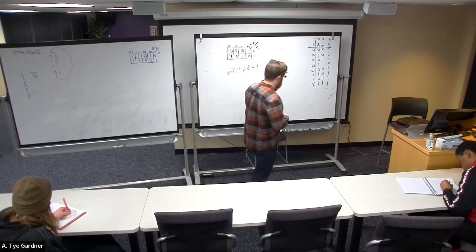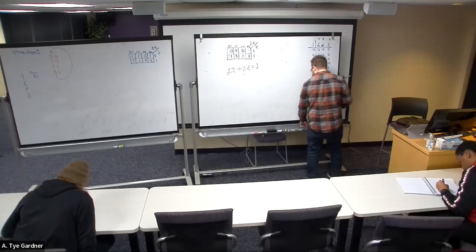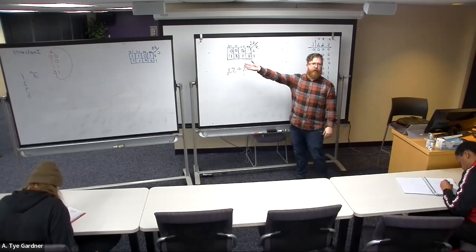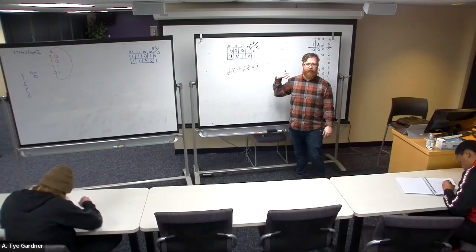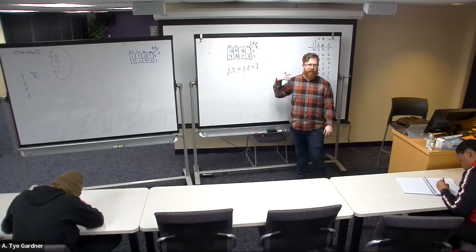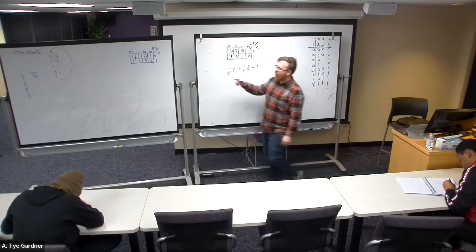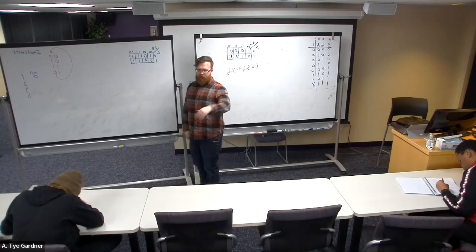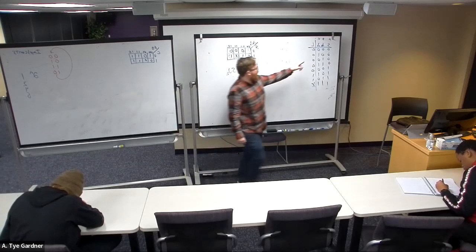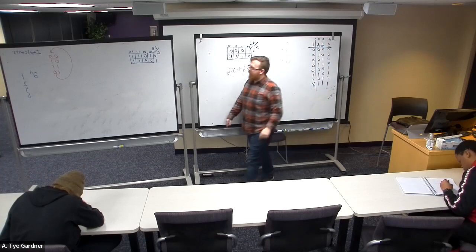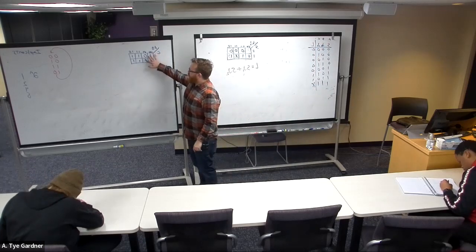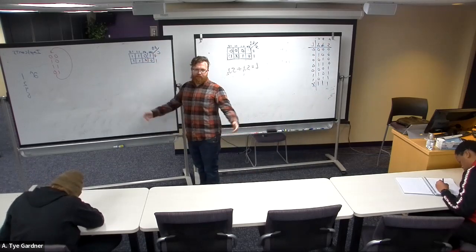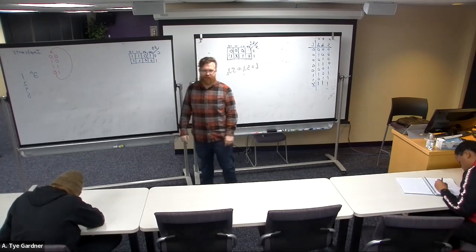Let's say we have this situation. This is a circuit. This is fine. I don't know what it does. We can find out though, right? We could turn this into a truth table. We can go the other way. I would literally just go through the truth table in order from top to bottom. If I order it as ABC, it is 1 0 0 0 1 1 1 1. That's the order of the truth table.